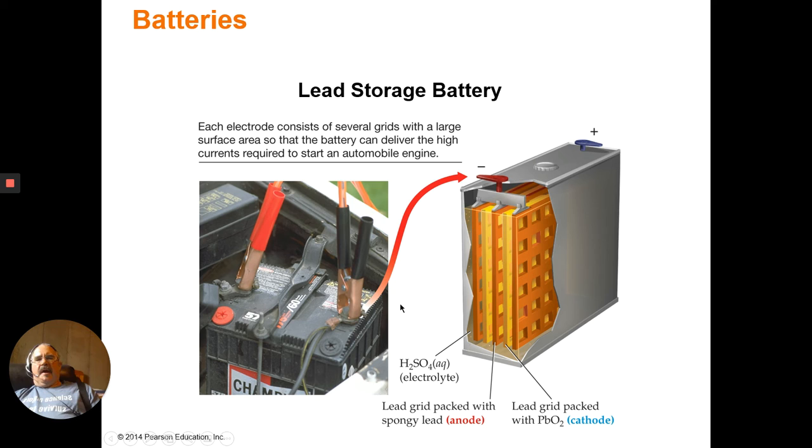Another reason is that through repeated charges and recharges, you dissolve lead into solution, and then you reprecipitate the lead, and this goes on multiple times, and over time the lead that is deposited at the anode can become soft and it can break off.